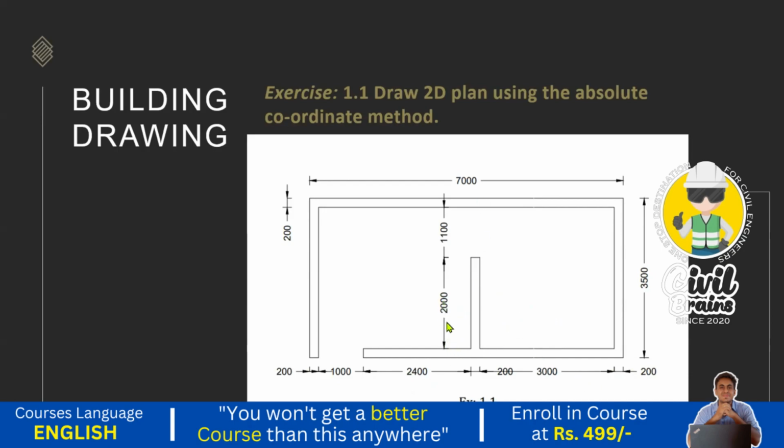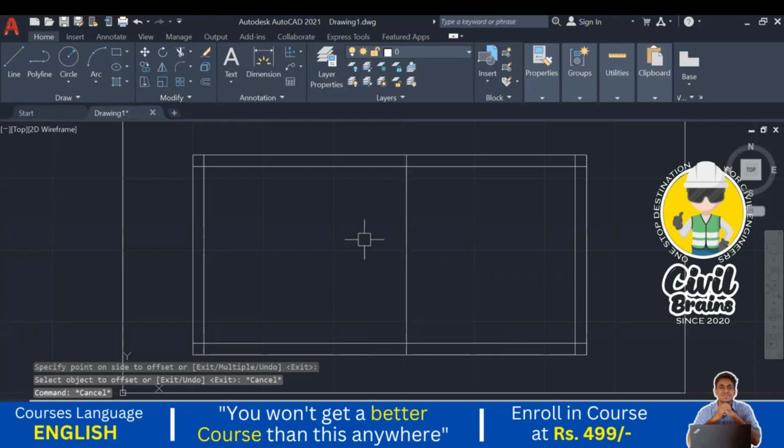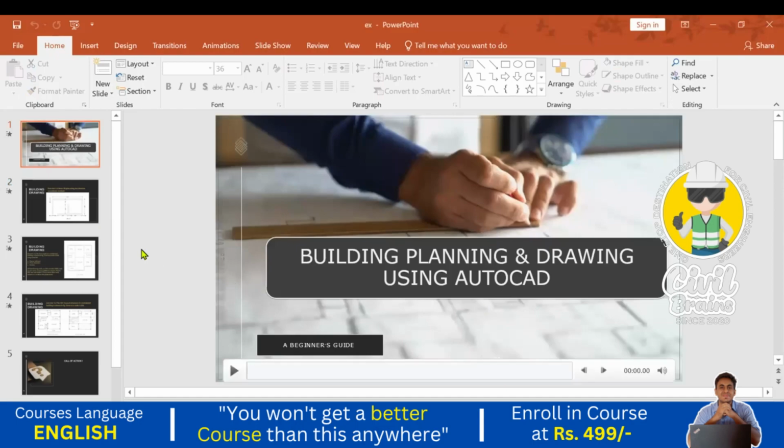And what is the height of this wall? That is 2000, and this opening is 1100. Okay, I go here and take the offset again. I go to the offset command. What is the distance to specify? That is 3000, that is our distance from this to this. And what is the next? Offset command. Press enter. Wall thickness is 200. Press enter. Okay, so these walls also we have drawn. Clear?